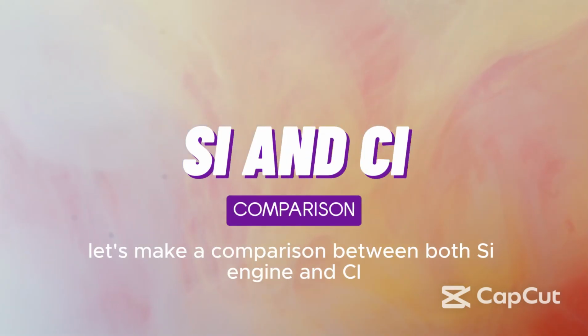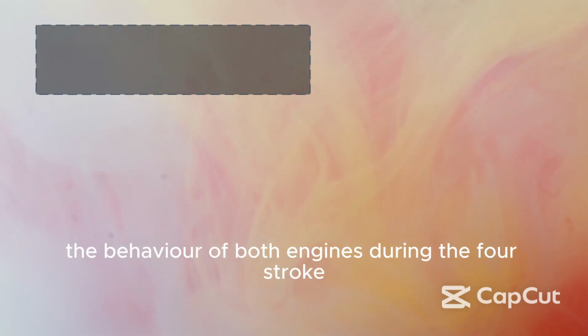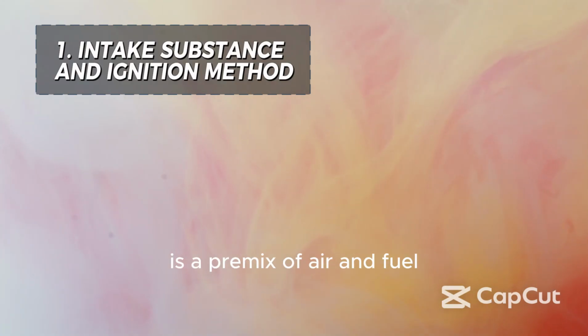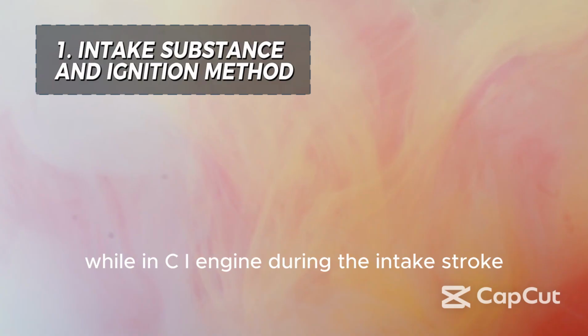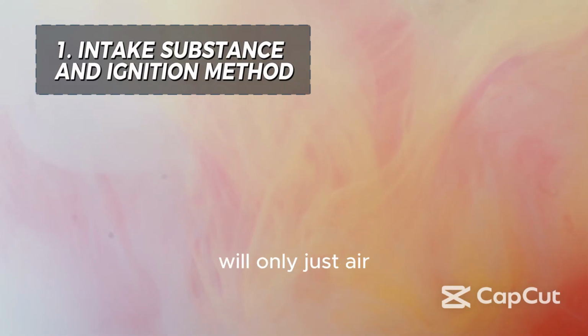So let's make a comparison between both the SI engine and the CI engine. Firstly, the behavior of both engines during the 4-stroke cycle system. For the SI engine, during the intake stroke, the substance that will enter the cylinder is a premixture of air and fuel, while in the CI engine, during the intake stroke, the substance that will enter the cylinder is only air.